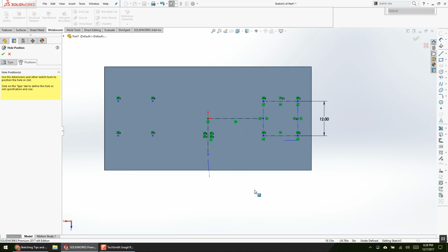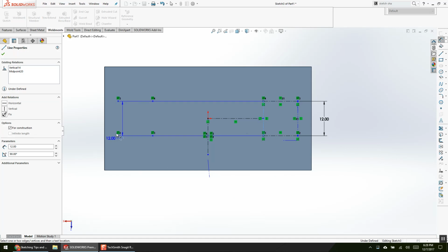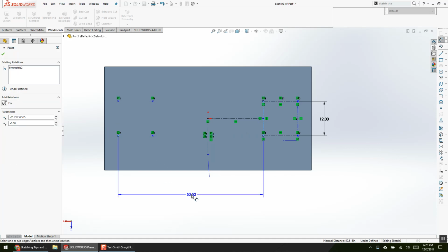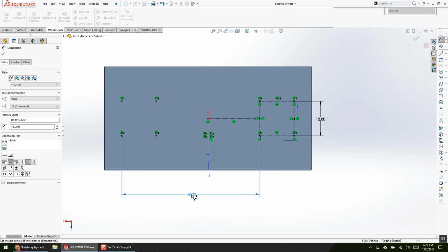Okay, so I want to go center line to center line. How do I do that now with the sketch geometry I have? Dimension from one side to the other. So I could go like this to this, right? As long as I favor the left-hand side on both, I'll get what I want. Not very readable. I've got a dimension that's skewed, but it theoretically works. And I could say I want 48 inches center line, right? So it's fully defined. Everything's black. It's theoretically okay.